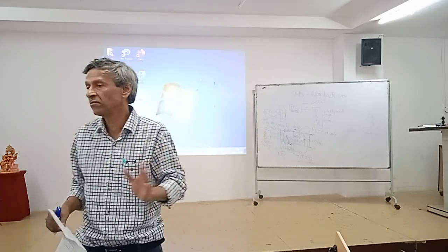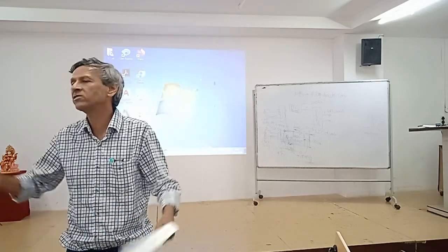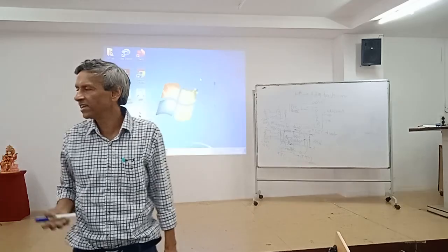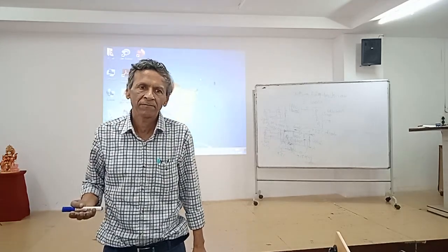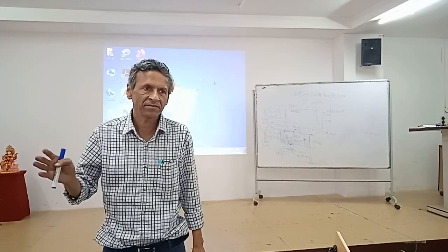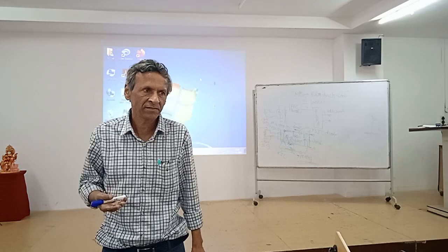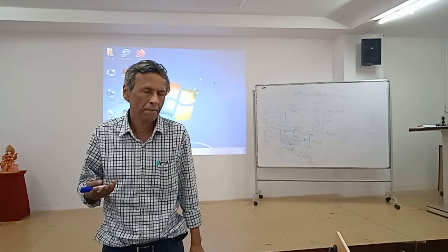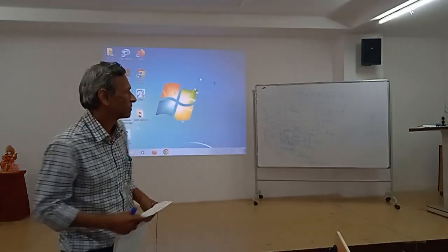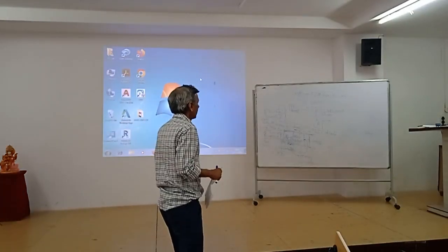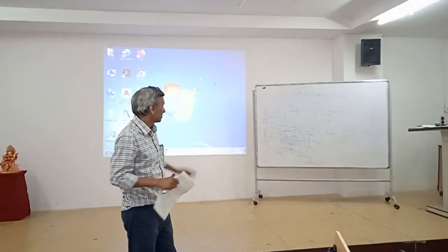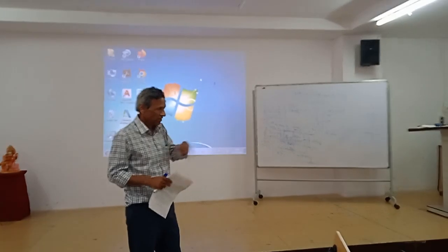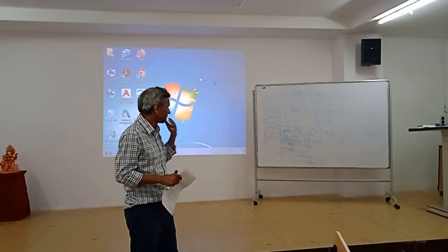Beyond 15, we have seen miraculous results. The moment you run 15 kilohertz, it is generating noise, but it is not in our audible range. Noise is there, but we cannot listen to that. We cannot hear. Now that is the next problem: how to sense current and all these things. After I explain the microcontroller, we will go for that.